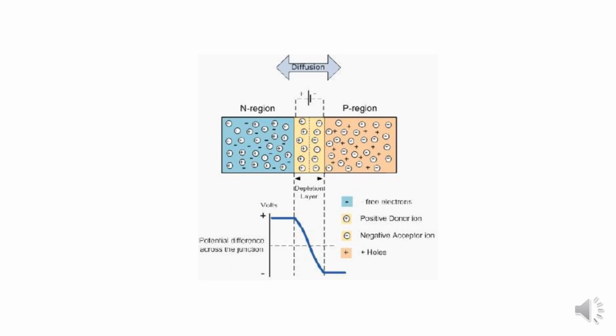When P-type and N-type semiconductor materials are first joined together, a very large density gradient exists between the two sides of the junction. Free electrons from the donor impurities migrate across the newly formed junction to fill up the holes in the P-type semiconductor, producing negative ions. The total energy on each side of the junction must be equal and opposite to maintain charge neutrality around the junction. The region formed between the P and N types is said to be the depletion region.